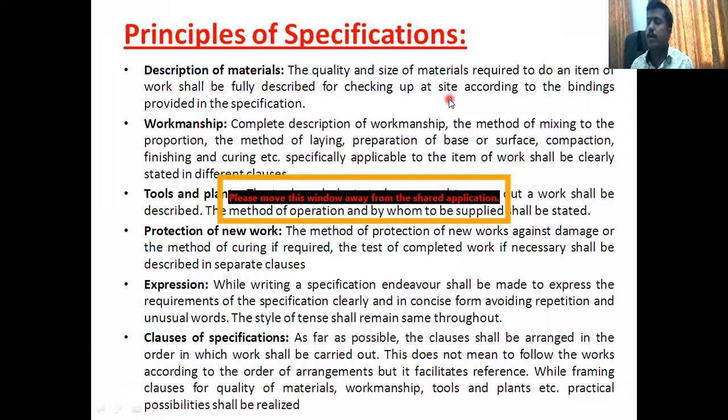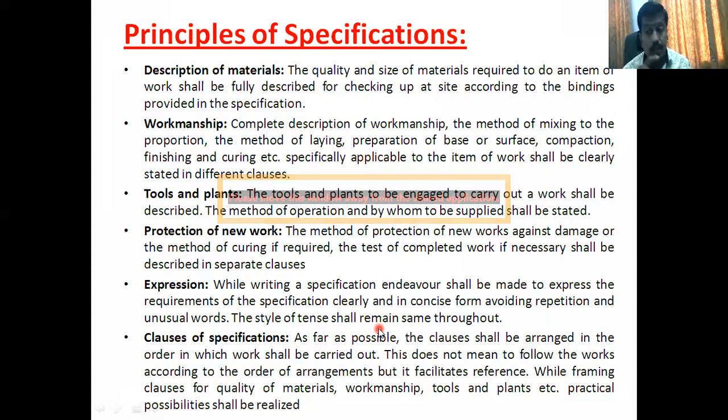8 to 10 and up to 13 tons. The roller capacity they are using is 13 tons. 10 to 13, that range is also there. So 8 to 10, 10 to 13, that range is also there. Okay, you can go for a smaller one also. That is again dependent on the type of the layer that you are laying.